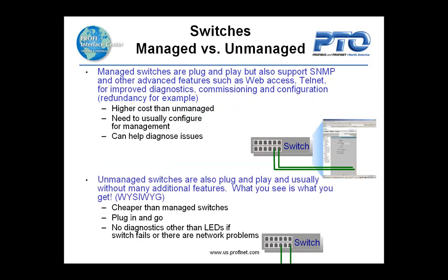Okay, switches: managed versus unmanaged again. Managed switches are plug and play, but they also support other features like diagnostics, SNMP, or advanced features, so you can access the switch via the web page, or maybe you can commission or configure the switch, maybe if you've got a redundant network. It can also help you diagnose issues.